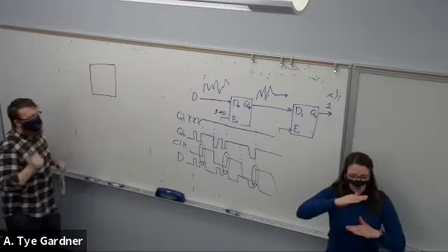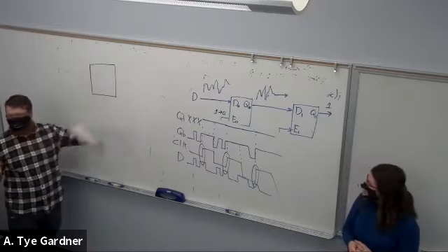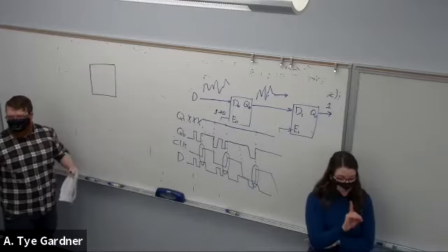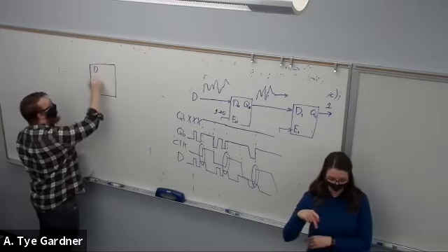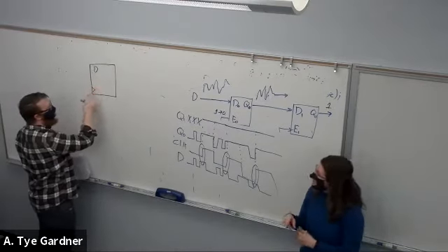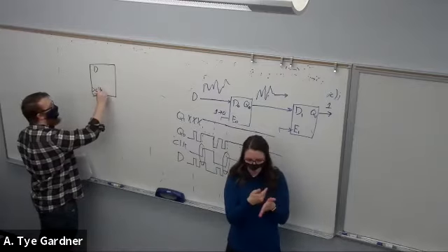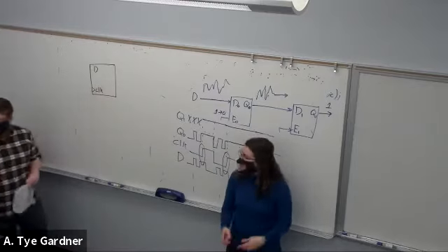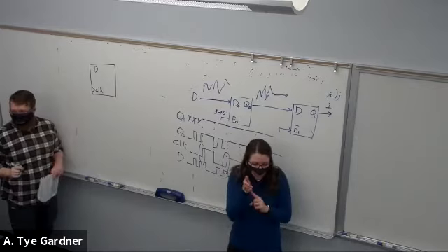The D flip-flop. Obviously, every time we write a flip-flop, we don't want to draw that whole circuit, so we create a new circuit schematic. And we're going to see something new, which is this little flag or triangle shape called clock. The flag means it is edge triggered.